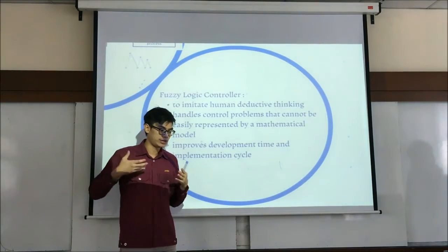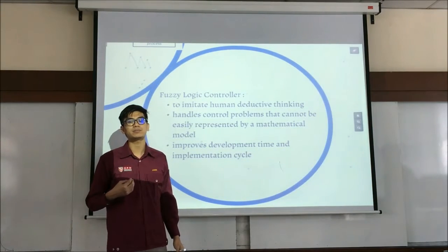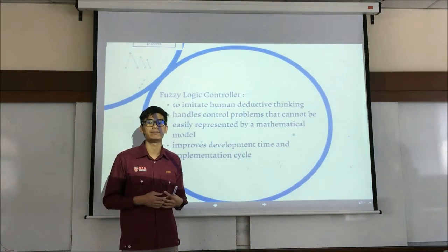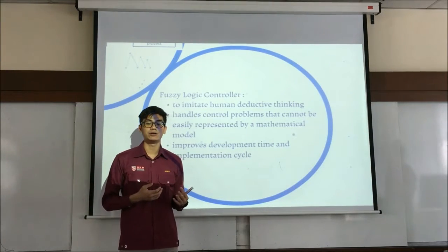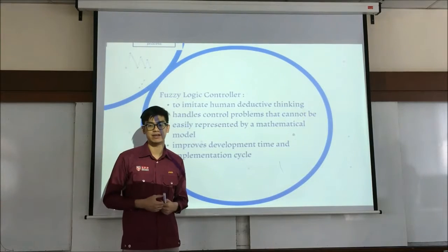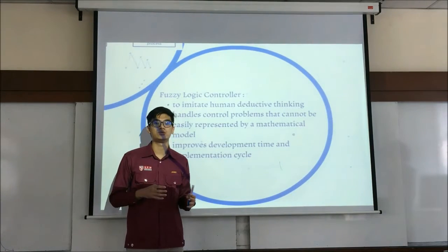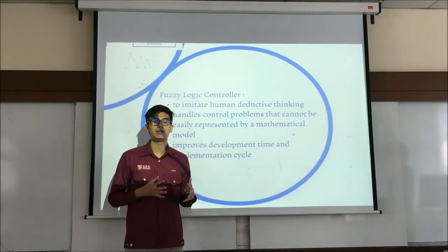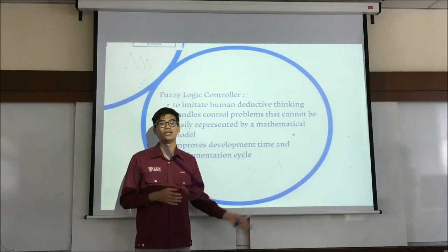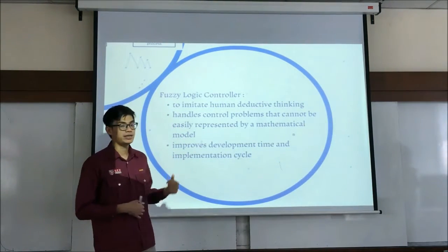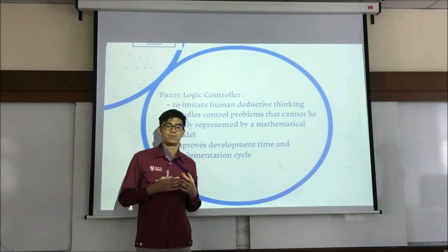Whenever the clothes are given into the washing machine, the controller will measure the weight of the cloth, and it will give out the operation time of the entire process. So you can say, for example, clothes that are below 3 kilograms will give out the operation time of 150 seconds, for example. So it will decide itself, and the operator does not need to decide how much time the washing machine needs to do the entire process. And followed by this, we will present to you the ladder diagram of the washing machine.